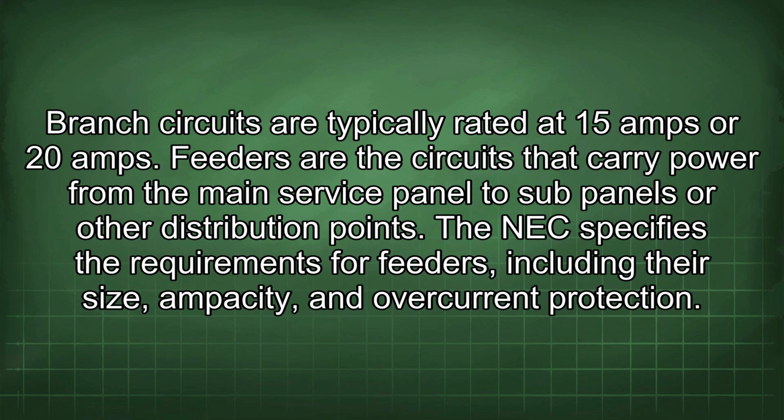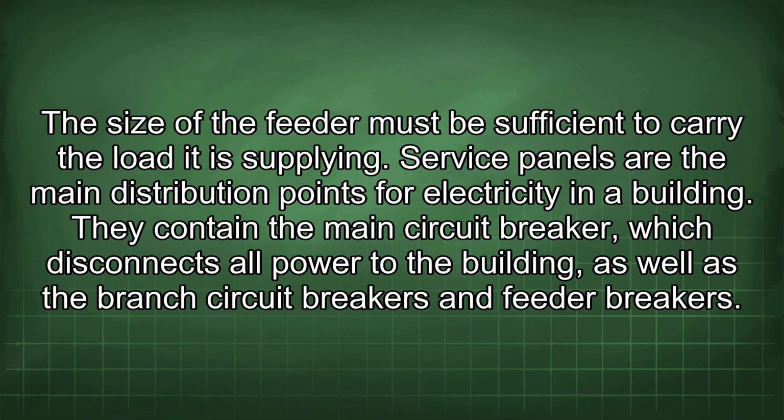Feeders are the circuits that carry power from the main service panel to sub-panels or other distribution points. The NEC specifies the requirements for feeders, including their size, ampacity, and overcurrent protection. The size of the feeder must be sufficient to carry the load it is supplying.